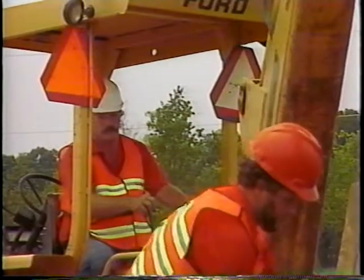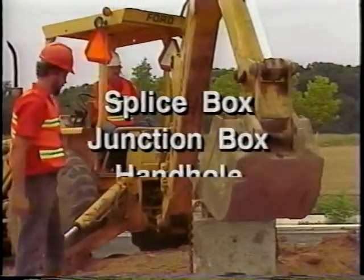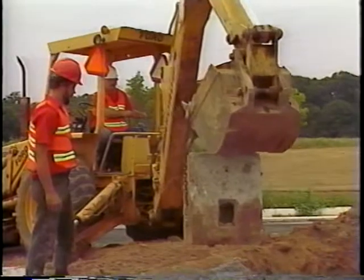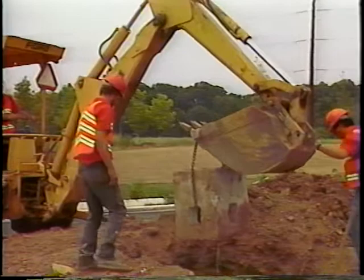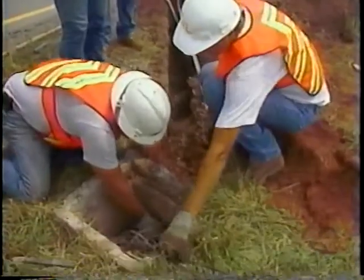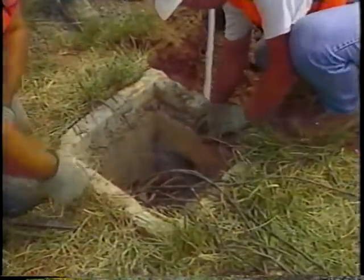The next step is the installation of the pull box, also called the splice box, the junction box, and the hand hole. The pull box houses the splices between the lead-in wires from the loops and the shielded lead-in cable to the controller cabinet. Made of concrete, plastic, metal, or fiberglass, these pull boxes are also required at intervals in especially long runs of wire. It is essential to provide all pull boxes with adequate drainage when installed. Most installations utilize a standard number 3 or number 5 pull box. For our example, we are using an existing number 1 pull box.